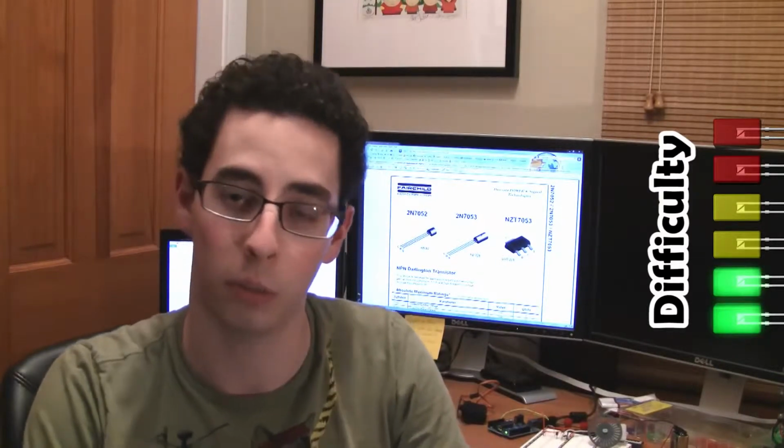Today I'm talking about motors and transistors and a couple of new programming topics that we haven't covered yet, like for loops. We're going to use a DC motor and change its speed dynamically using a transistor and some code from the Arduino. And then we're also going to use a servo motor that you can control with PWM, or pulse width modulation, signals from the Arduino to control its position. We'll finish up this episode by making a little project that controls the precise degree rotation of a servo motor using the readings from an infrared distance sensor.